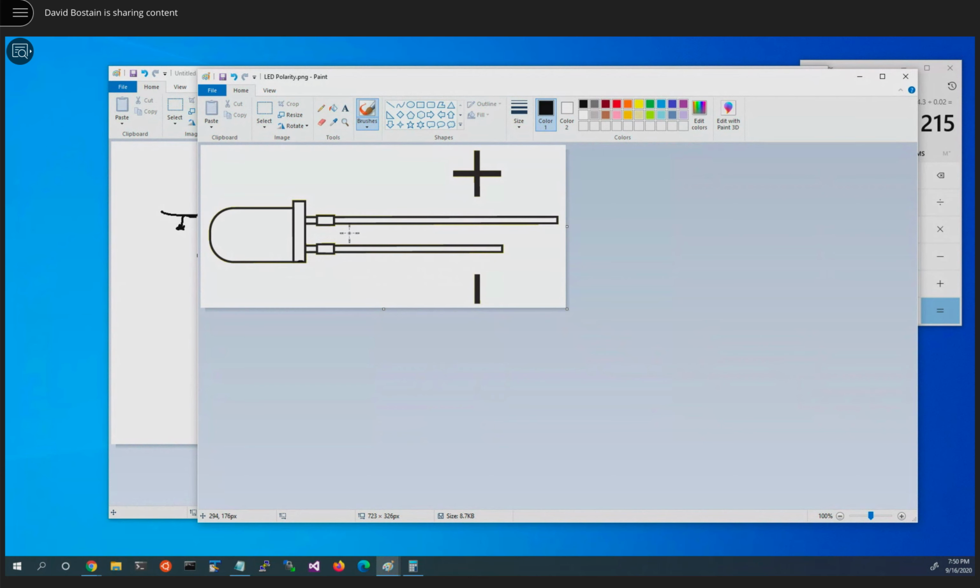So this is how you would take a diode, and in a picture, I might show you a picture of a circuit and ask you, is the diode in correctly? You could look and study the picture and notice that the flat edge is perhaps on the wrong side, and you would go, no, it's not. Don't turn that circuit on.